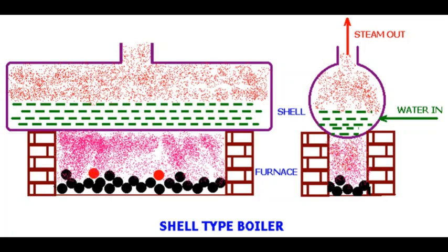These disadvantages are mainly related to the area available for heat transfer because of the shell size, and there is more heat loss across the shell boundary, and there is no insulation surrounding it, and they are more prone to explosion as the shell is directly heated, and there are limitations of steaming capacity and of accommodating higher steam pressure. So that's why gradually they were discarded from service.